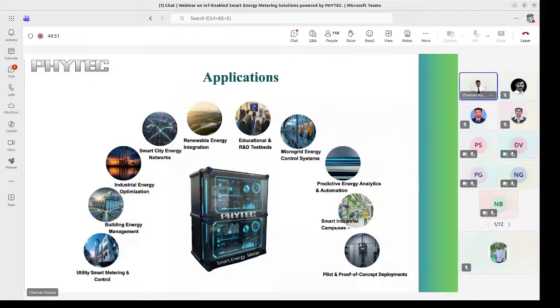And here it is also divided in two ways: LTCT smart energy meter and HTCT smart energy meter. LTCT smart meter means low tension current transformer smart meter. It has an external CT, because here the current range is more than 100 ampere. That's why we go for the LTCT smart meter. This type of smart meter is used basically in substations, where we need three phase supply and high current.